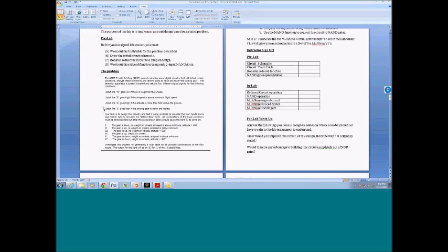Some of them are very simple. Some of them are slightly more complicated. So the students have to go through and look at each of those 6, and write those out as Boolean expressions. They put them on a truth table, and then I get them to do some reduction. I think this was actually done, they Boolean reduced this before they had K-maps.